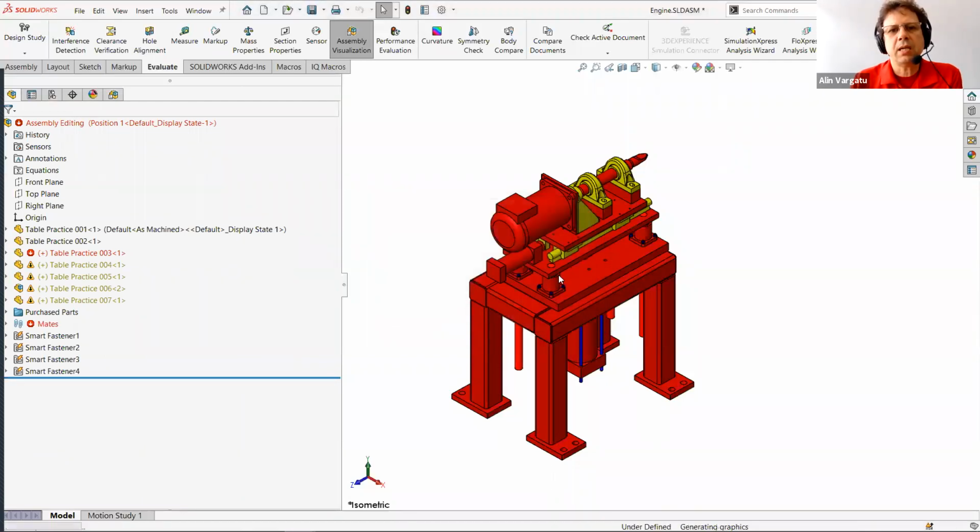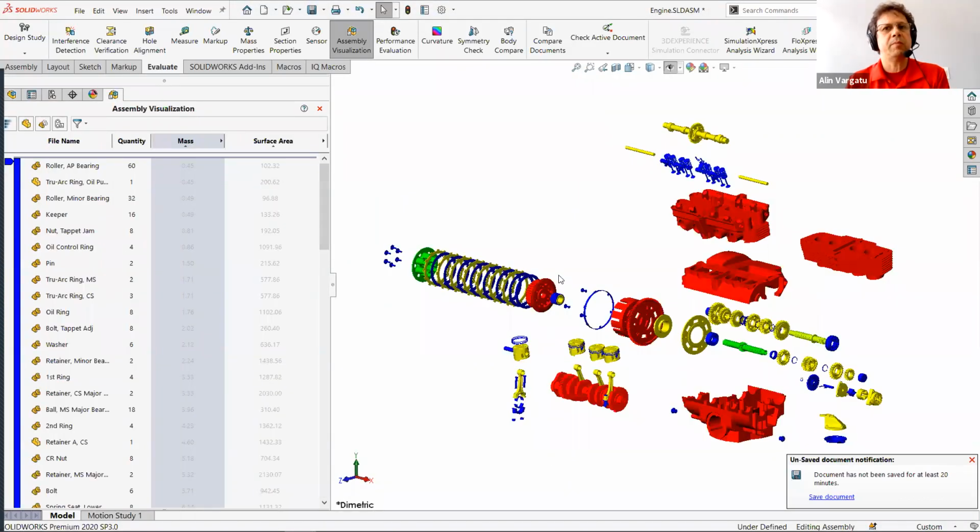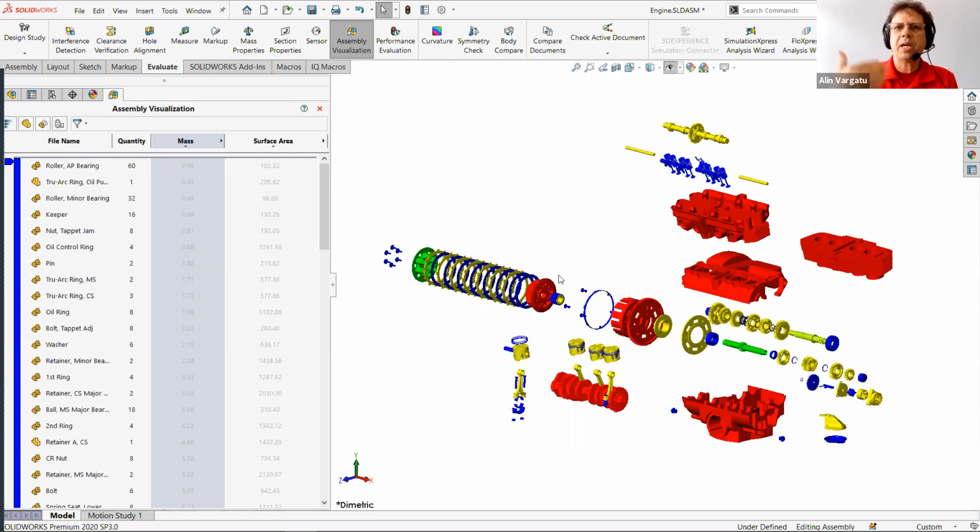The other thing that I encourage users to do, especially CAD administrators and PDM administrators, is once you have a certain assembly visualization style that you believe is the most popular for your team, and a good one would be something related to troubleshooting large assembly performance, to save that in an assembly template. So start a brand new template, load that style there, and then resave the template. Now everybody who uses this template to start a new assembly doesn't have to do any work. They simply click on this and automatically they get the columns that they require.